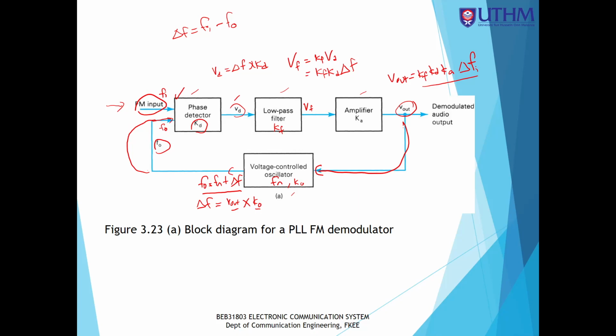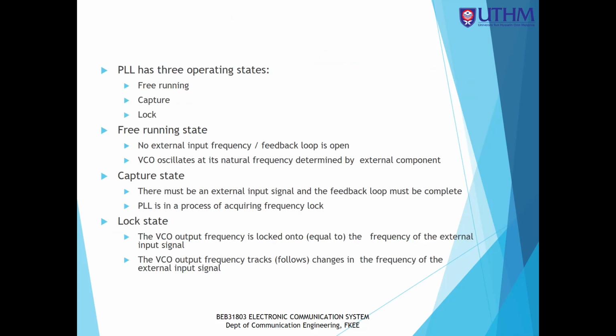Okay, so for example, I want to listen to Era FM like previously. I want to listen to Era FM, and it will compare the input to find the intermediate frequency of 455 kilohertz. Then it will do the output process, because this is a demodulator. Once it receives the signal, it will start comparing to find the desired frequency band for the demodulation. So that's why we have these three states.